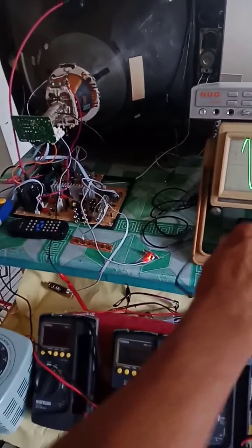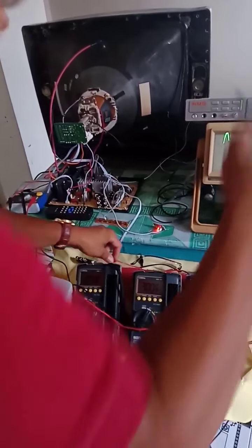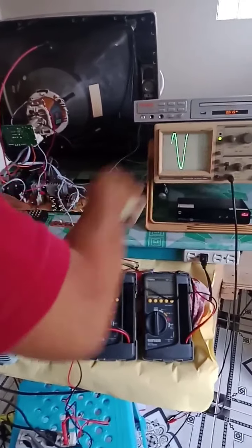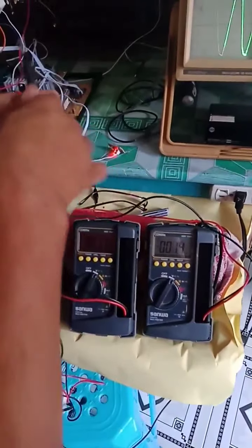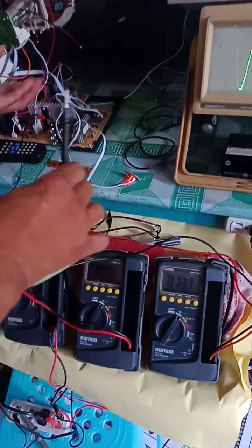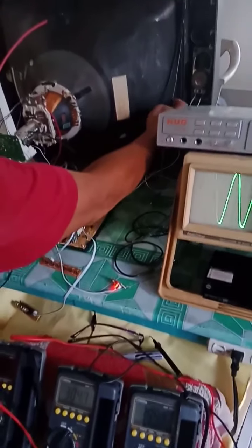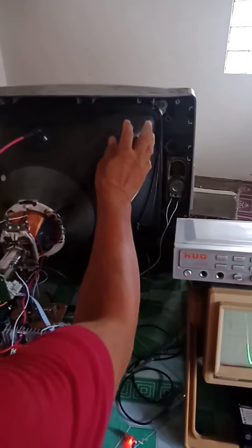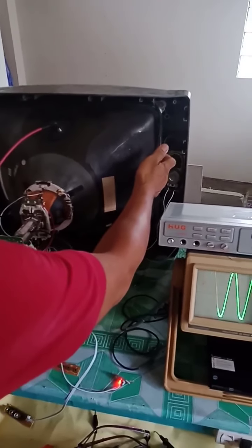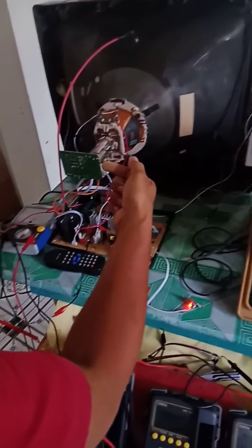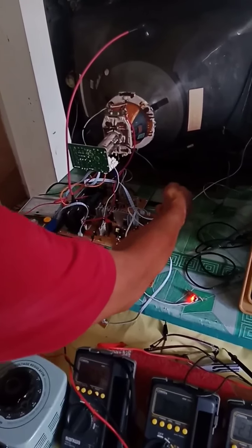Okay, we have here. By the way, how do we measure the voltages of the circuit? We will set it to DC voltmeter and connect the negative side of the DC voltmeter to the negative side of the circuit. Where is the negative side of the circuit? It could be this bare harness wire that hugs the outer conductive coating, which is the negative side of the picture tube. The negative side of the picture tube is connected to the negative side of the CRT drive, and finally connected to the main board, which is negative.